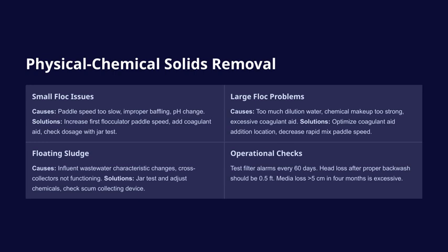We should test the filter alarms every 60 days to ensure they're functioning, and after a proper backwash, the head loss should be around 0.5 feet. Also, keep an eye on media loss. More than 5 centimeters over 4 months indicates excessive wear that needs addressing.